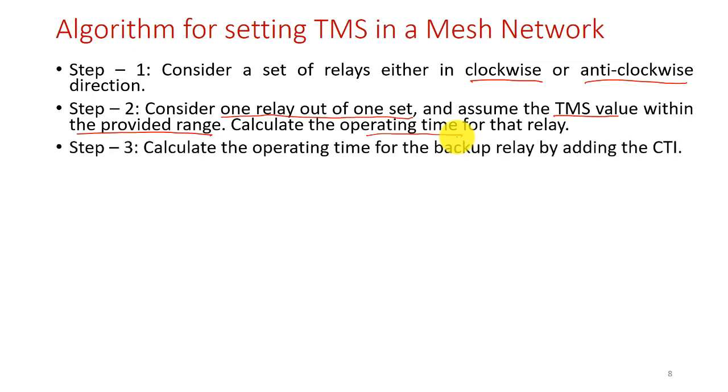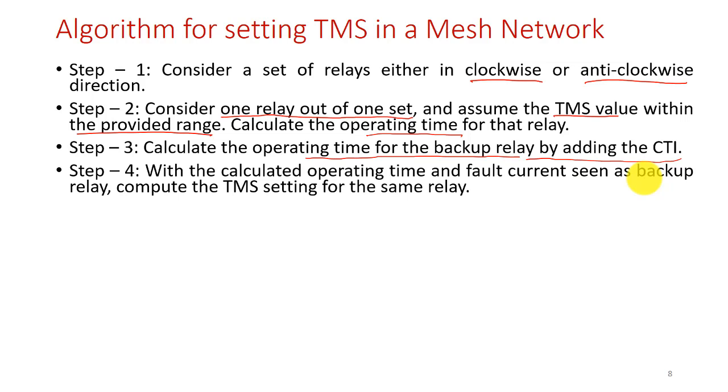Then in step 3, we calculate the operating time for the backup relay. We know the backup relay for that relay, and by adding the CTI, the coordination time interval, we get the operating time for the backup relay. Okay.